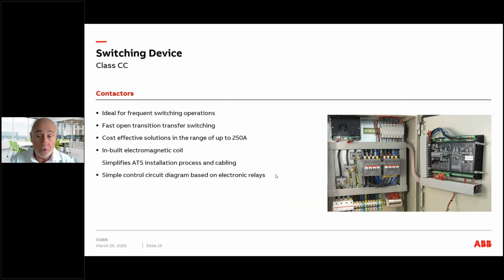Now we see these sort of solutions, they're still widely used, but again, as we'll see later on, be careful on product selection, because when it comes to life safety, this will not comply, which we'll explain a bit later on. But certainly in the industry process control, where it's not for life safety, it may be used for switching different supplies to different loads for a raft of different reasons, sort of duty control, etc. So contactors are allowed and they're in the standards, but not for life safety, as we'll find out a bit later on.